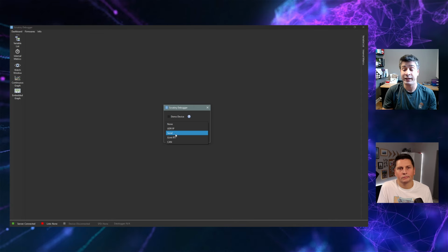So you can do that in your low priority task. You can multiplex the communication with something else if you want. Which is a big advantage, because if you have a critical task, you can make your debugging process lower priority than your critical task. Yeah, I was about to ask, because when you're debugging embedded systems, most of the time there is a real time or hard real time aspect, right?